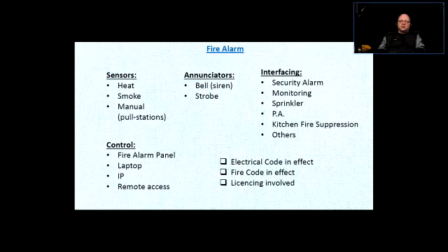Now, if it's a sprinkler system that is installed in an outside garage, like a multi-story outside parking lot, even though there are different levels of the parking structure, everything is outside. There are no walls. It's considered to be an outside environment. And if it's winter, then the water that's in the pipes could basically freeze. So the system could be not very well operational, would it? Because the water would be frozen in the pipes, and the pipes could break because of the expansion of the water when it turns into ice.